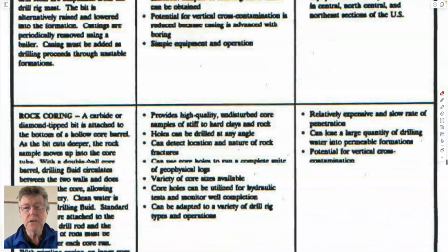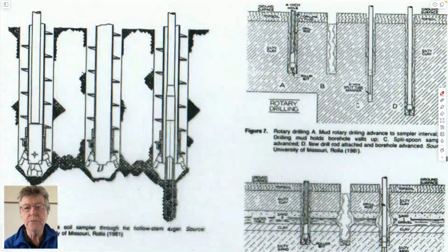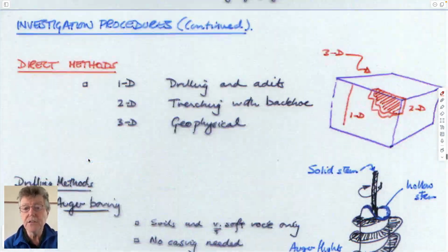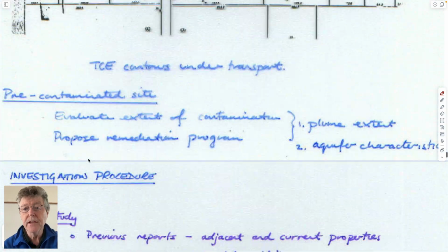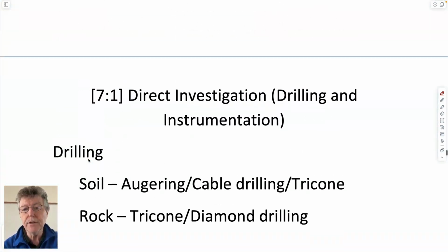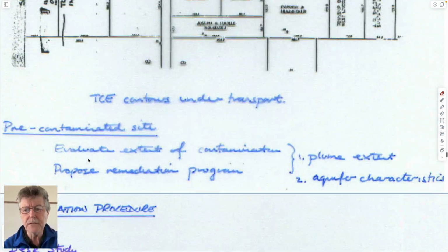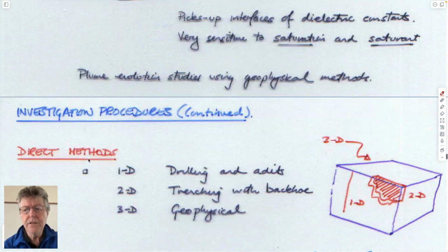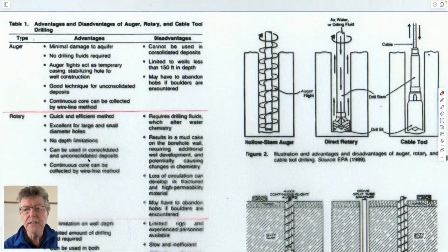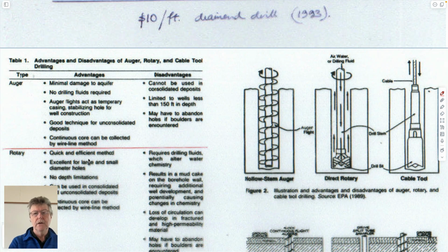I suppose it might not be a complete waste to just say the things from this one figure I'm thinking of from last time. And that is that if you're planning to drill, the drilling methods fall into these three categories. Augering, to drive a corkscrew down through soil. No samples, just what comes up on the flights, which you can sample. Hollow stem allows you to sample down the middle through the methods that we'll talk about today.